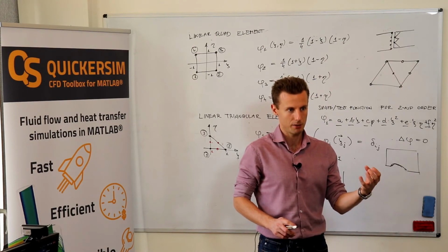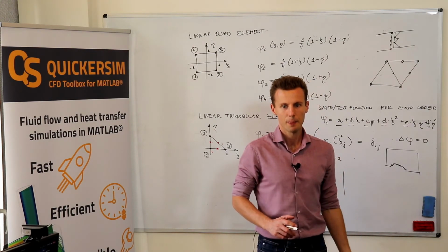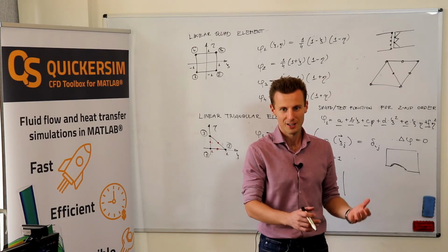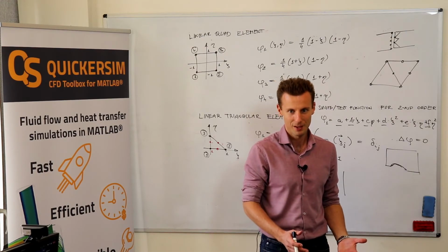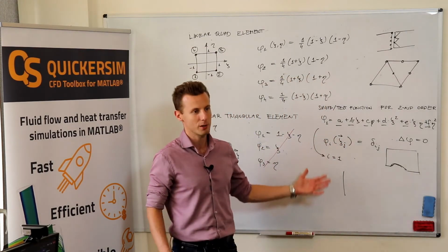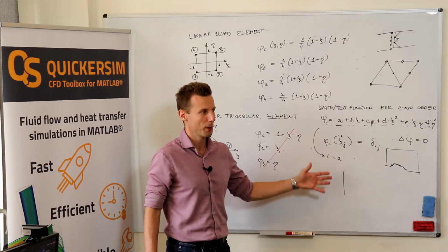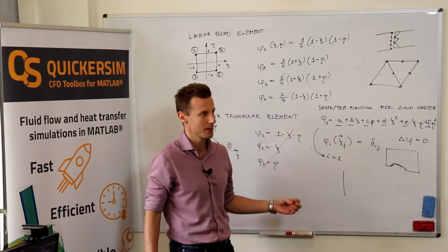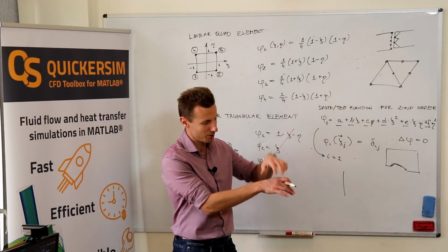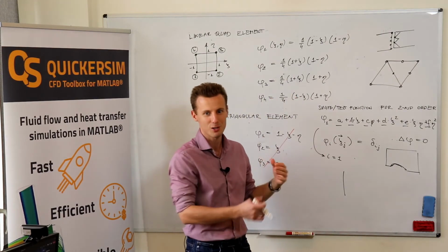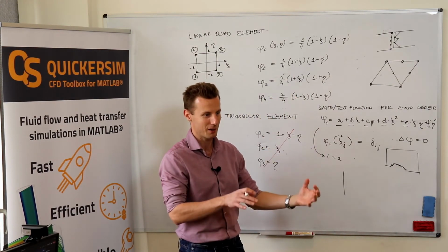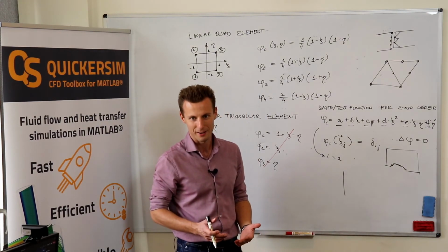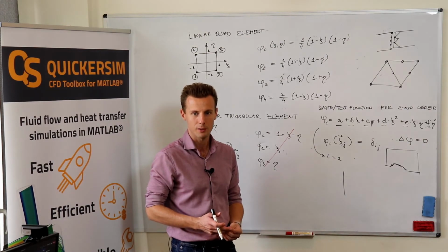But you can imagine such an application, and if you've got geometry that changes in time, the bomb that starts dropping, you need to constantly have a mesh which is properly aligned to your current geometry. So if you generate the mesh once, then you would need to remesh every time step or every couple of time steps, because you would be extending the mesh, but then you've got long elements, so you need to remesh. Then you can simulate by elastically extending the elements, but then you need to remesh again, etc., and it's not very convenient.